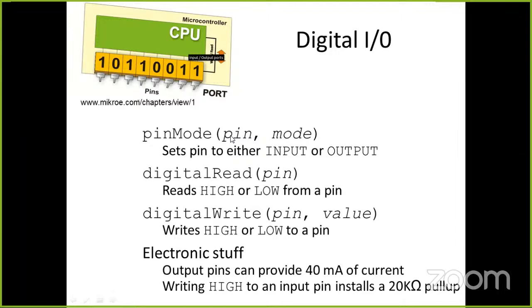Whatever mode we are using, pin for input or for output, for example if we are going to turn on a relay, that is an output signal. Whenever we have to read any kind of input or output, we have to define in the Arduino which pin we are using and whether it is input or output. In graphical coding we are not doing it, but when we write code in C++, we have to define that. So how can we define that? You can use this syntax: pinMode, pin number, and mode, meaning input or output.